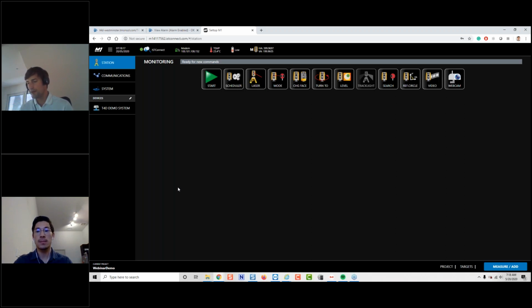And there was another question from Martin, if we also support a least square adjustment. At least this is how I understand the question. So the answer is yes, T4D supports a least square adjustment. So you can imagine if you combine multiple total stations in one processing engine, we can adjust all the measurements of every total station together in one flow. So this is fully supported.